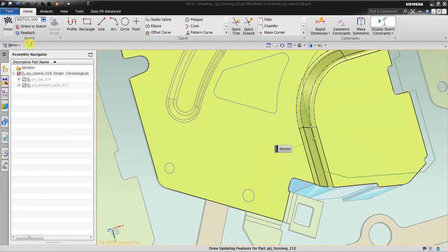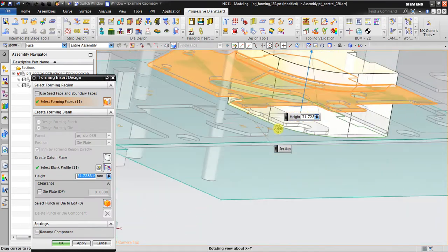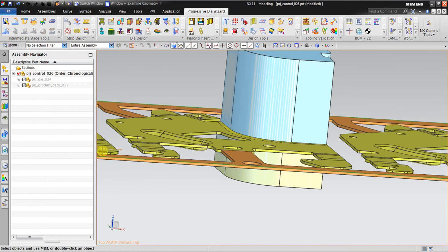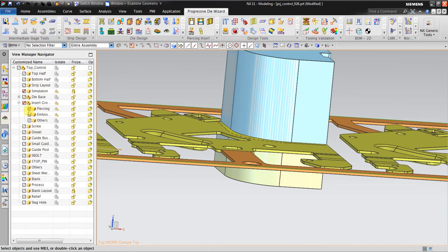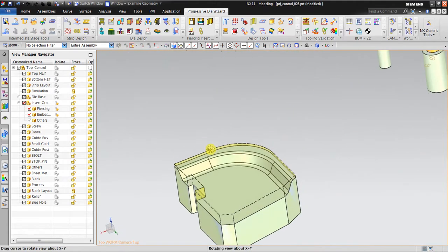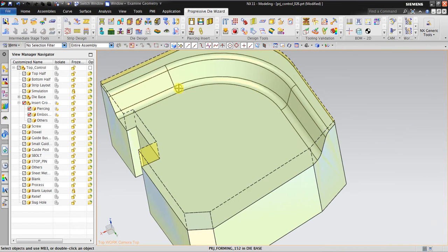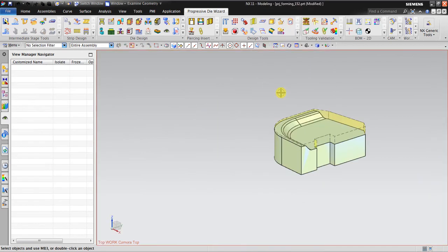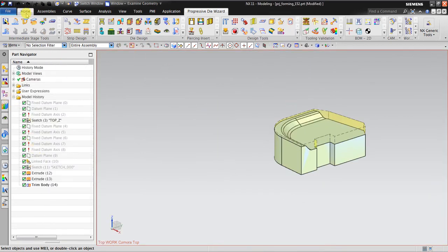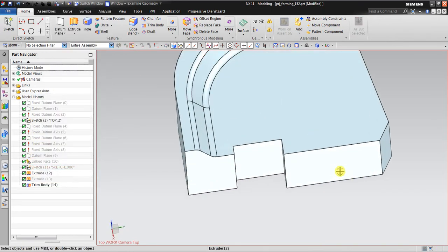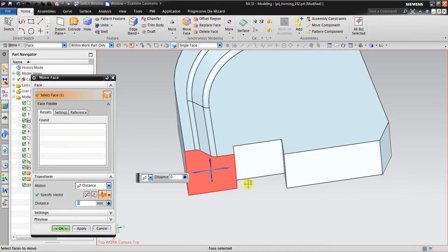I click finish, and it's automatically extrude. Slightly overshoot the surface, but it's okay because we already clicked this one. And then I click OK. Now let's check the result. Click hide. Now you can see it create a good shape, and in here also you can edit in synchronous technology in the modeling environment. I hide. Maybe I want to slightly pull this one, move face all of this.